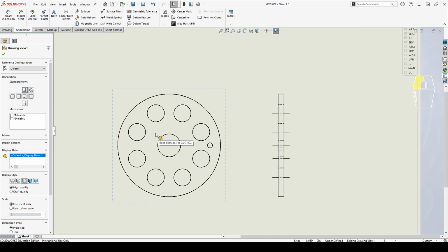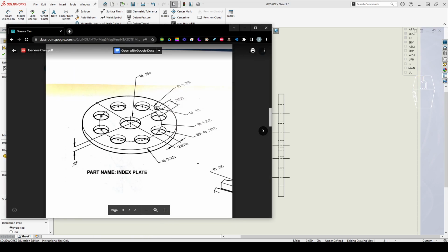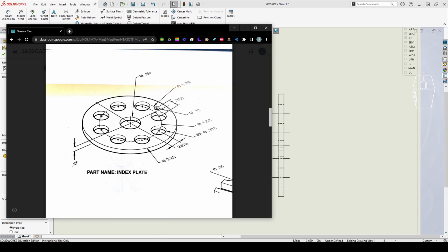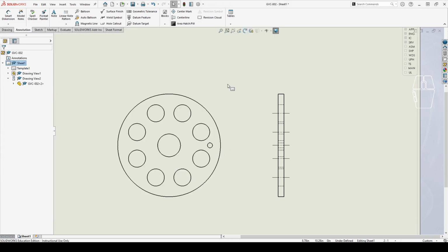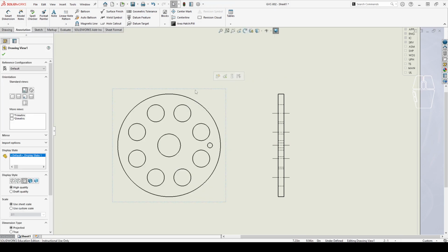I always go back and forth with center lines and center marks on these. So I was not really a fan of showing the center line coming out to every single hole in the part file that we had, or in these drawings. It doesn't show that you have to have a center line every hole. We definitely don't. We're just going to put the big center mark and then the center line circle. I made the other drawing messier than we needed to. If you want to go back and fix that other drawing, go ahead. Clean it up by getting rid of the extra center lines.